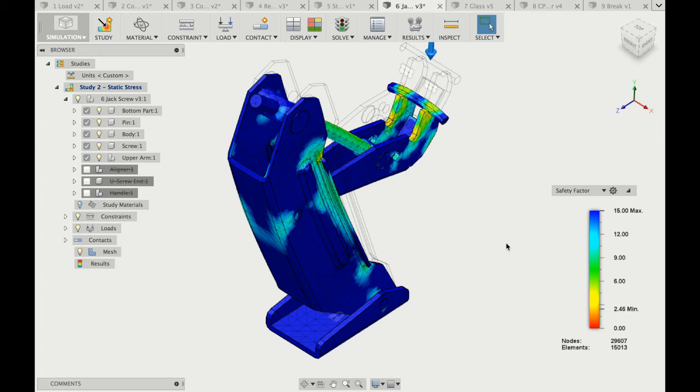I think what your boss will be really interested in is this number, the safety factor. Because typically they tell you it needs to be above 2. If it's above 2, that's safe. So if you say, I proved that it's 2.4, you are good, you are covered because your design is safe. This is just the internal behavior of your design that gives you directional guidance to improve because the design is never perfect. You can always do improvements there. Maybe drill some holes or weld some pieces here and there to be better and have the stress more evenly distributed through your design.